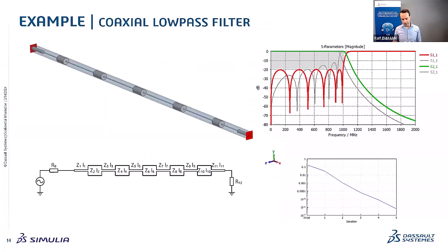Of course, we talked about ladder circuits, but normal stepped impedance synthesis can also be utilized, for example, with a coax low-pass filter. Here you can see that, where again, you can go and load your own components in the library and stitch them up with this assembly approach that FT3D uses. I mean, FT3D does this for you. For example, realizing the capacitance here or the high impedance or the low impedance lines might be difficult, so you can load your own sort of implementations for those.